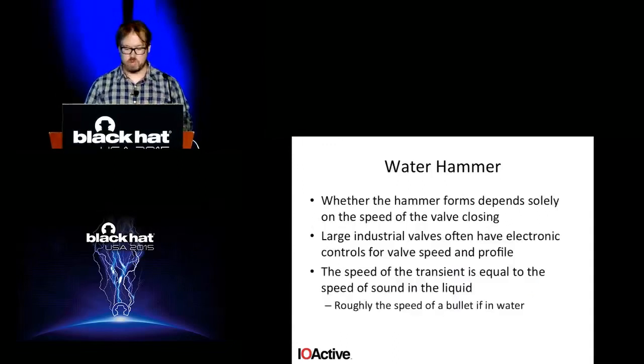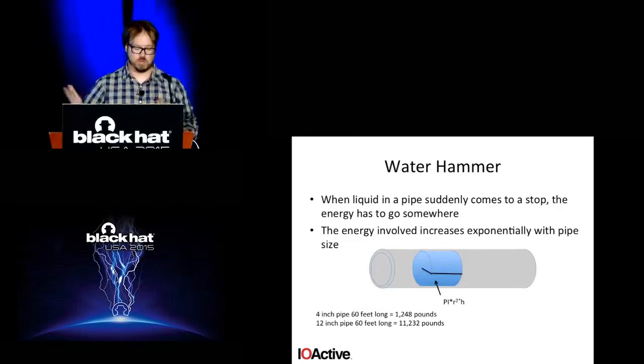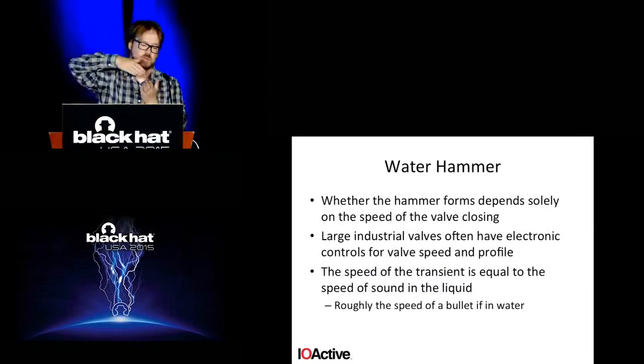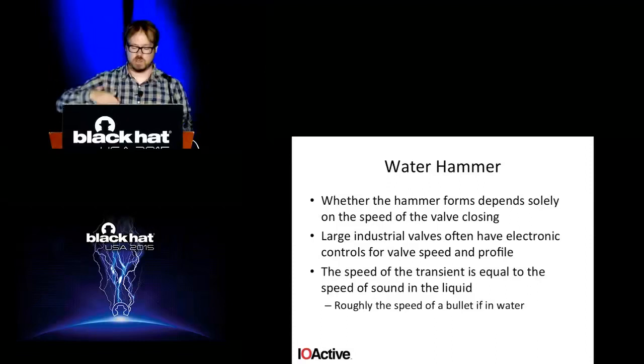Whether or not the shock wave forms actually depends on the very last closing part of the valve. The valve can close really fast, and it's only when the valve actually touches the seal that the water hammer forms. We did a bunch of experiments with them, and you never quite know where the water hammer will hit or what the weakest link is going to be.